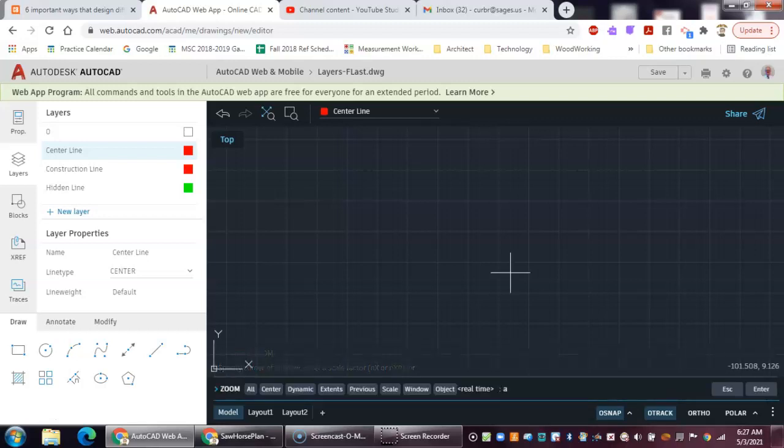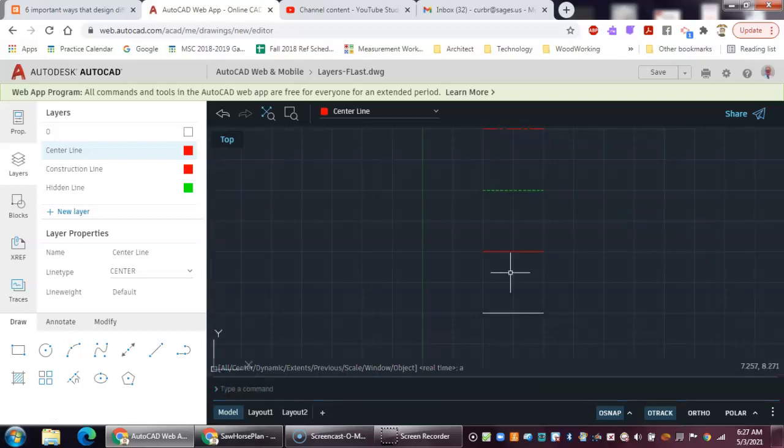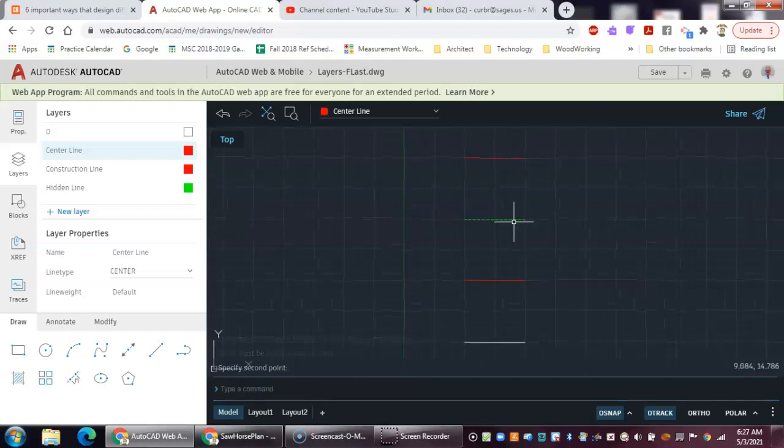So we'll go ahead and zoom all, and I'm going to do a zoom center again just to keep everything in place. So zoom center, and right here is where I want it to be centered. I'll click that point, and my zoom magnification is good. So I'll just hit enter and bring that down where it's more centered in my screen.